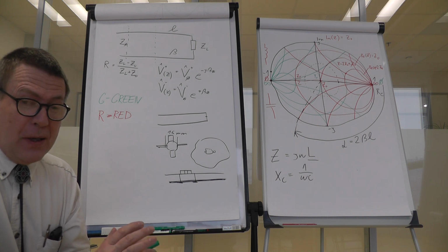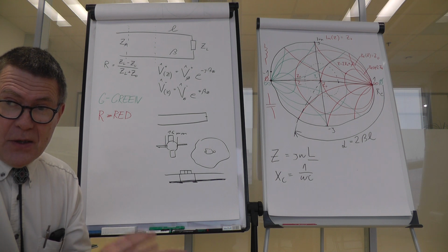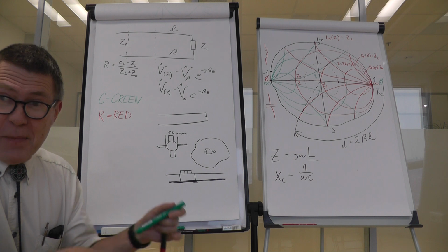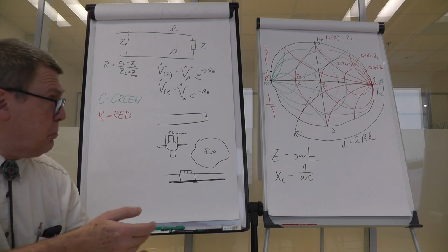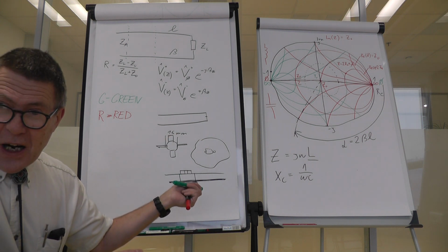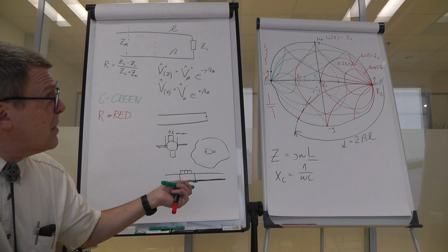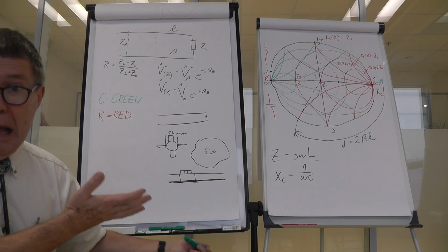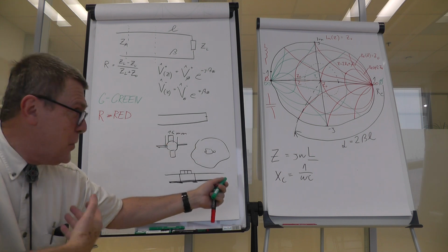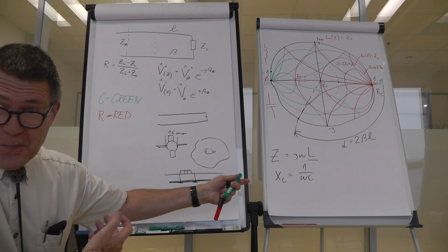Radio frequency engineers or microwave engineers would not tell you a mathematical expression for, let's say, the evolution of impedance in the chart with frequency. They would just say, well, it follows the constant real part circle. So if you don't know the language, if you don't know the chart, you do not understand what they tell you.